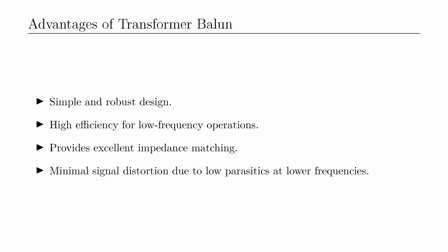The transformer balun offers several advantages: a simple and robust design, high efficiency, especially for low-frequency operations, excellent impedance matching between input and output, and minimal signal distortion due to low parasitic effects at lower frequencies.